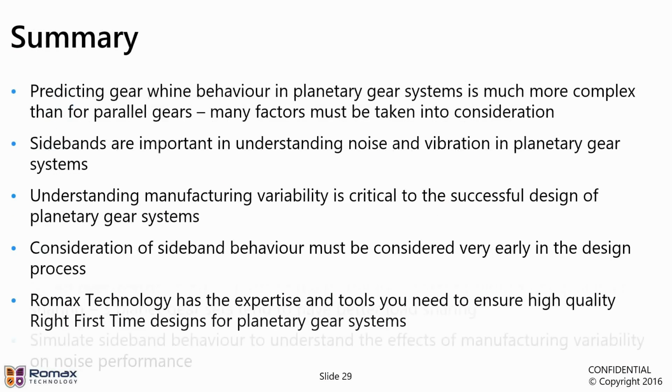So just a quick summary, we've seen that predicting gear whine in these planetary gear systems is much more complex than parallel gears. Many factors need to be taken into consideration when we are doing this kind of simulation and prediction. We've seen that sidebands are important in understanding the noise and vibration behavior of these gear sets, and in fact are critical to understanding them.